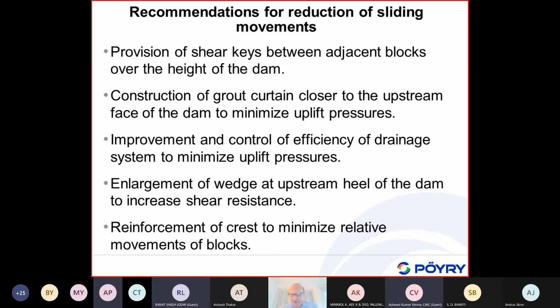Okay, so therefore, if we today in an earthquake area want to control such kind of failure modes, because here in this 2-dimensional model, it has been assumed that contraction joints, the block joints, are basically open, are free. They are not creating any friction resistance. But by providing shear keys, of course, relative blocks could not move. They could only move within the tolerances of the shear keys.